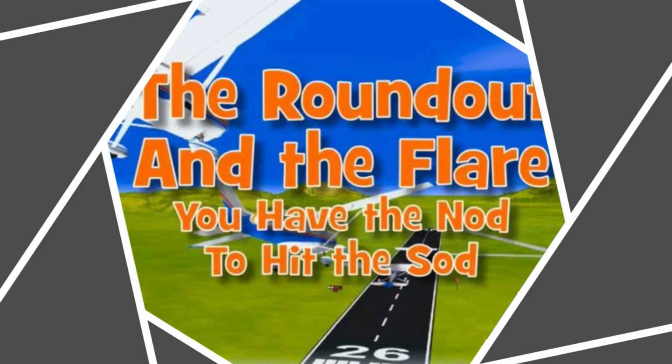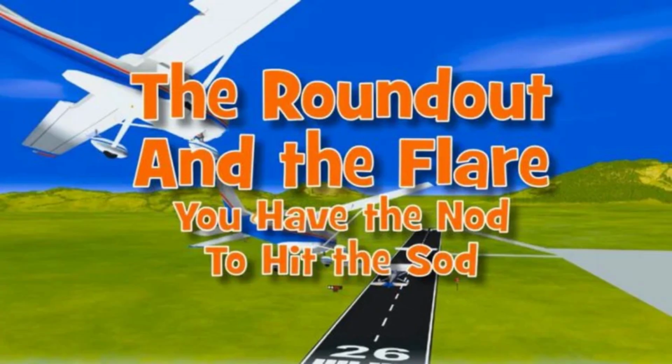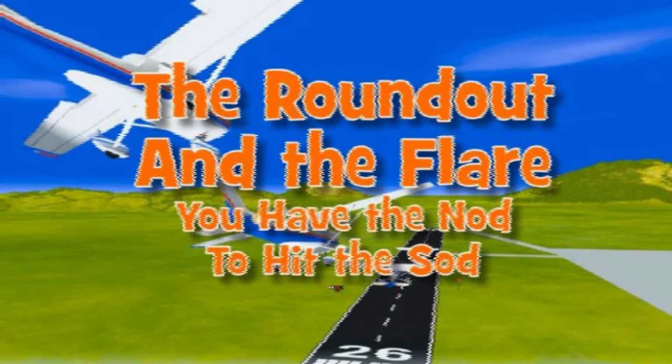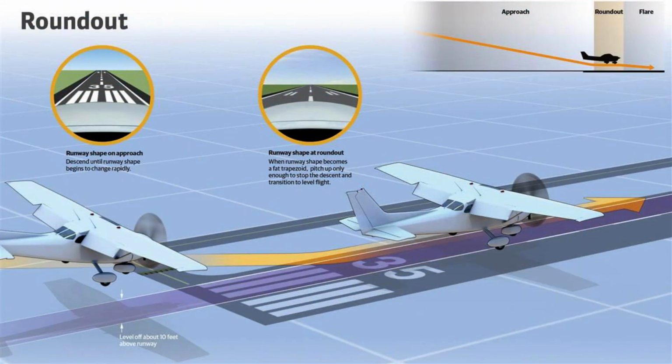Crosswind roundout, flare. Generally, the roundout is made like a normal landing approach, but the application of a crosswind correction is continued as necessary to prevent drifting. Since the airspeed decreases as the roundout progresses, the flight controls gradually become less effective. As a result, the crosswind correction being held becomes inadequate. When using the wing low method, it is necessary to gradually increase the deflection of the rudder and ailerons to maintain the proper amount of drift correction.